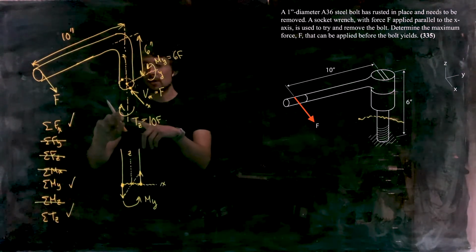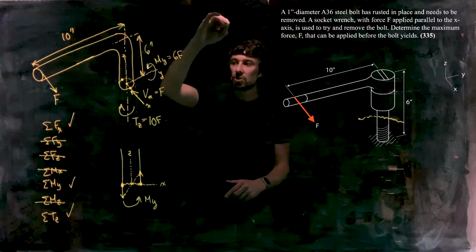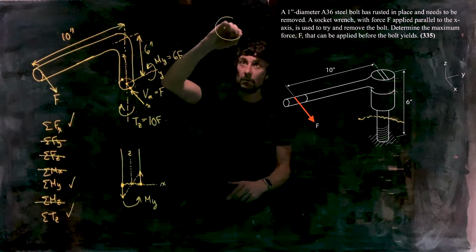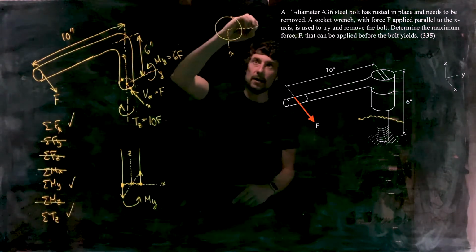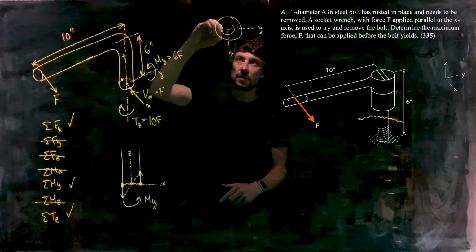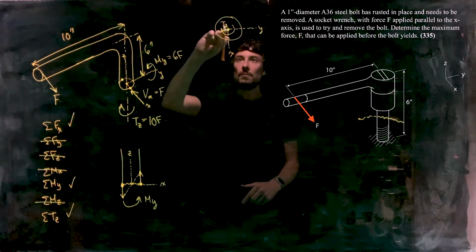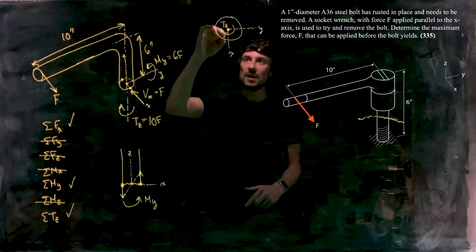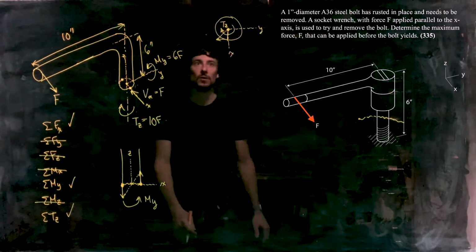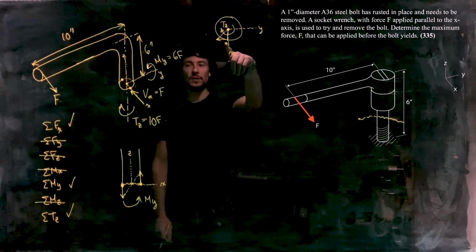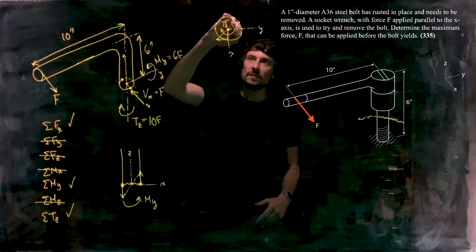All right, what about the shear stress from the torque? Well, we know that shear stress from an internal torque, if we look down the z-axis, so we've got the x-axis going this way and the y-axis going that way, and our internal torque is around that way. This is Tz. Then we know that internal shear stress due to an internal torque just increases as we move outwards from the center. So we've got a distribution of shear stress that looks like that if we're doing a radial line along the x-axis. Okay. So all points along the circumference will experience maximum shear stress from the torque.